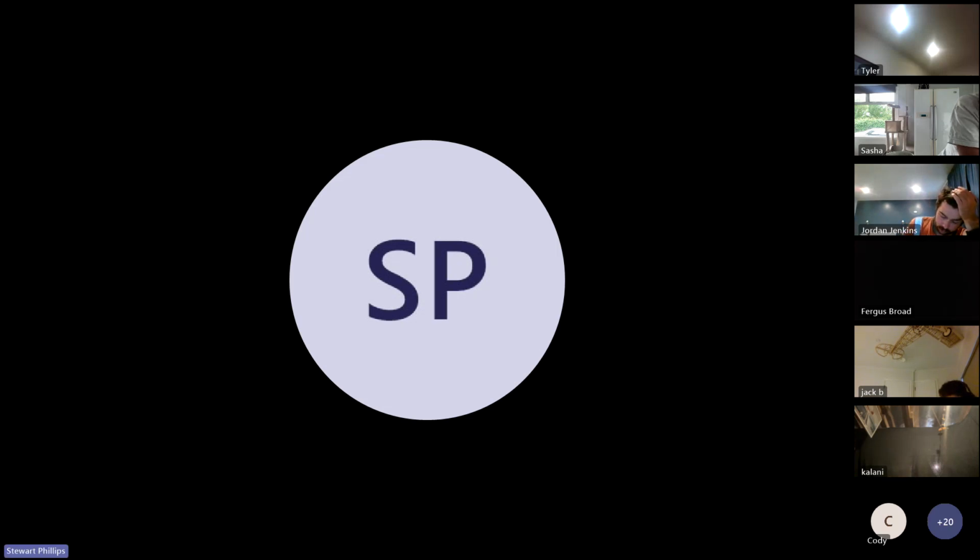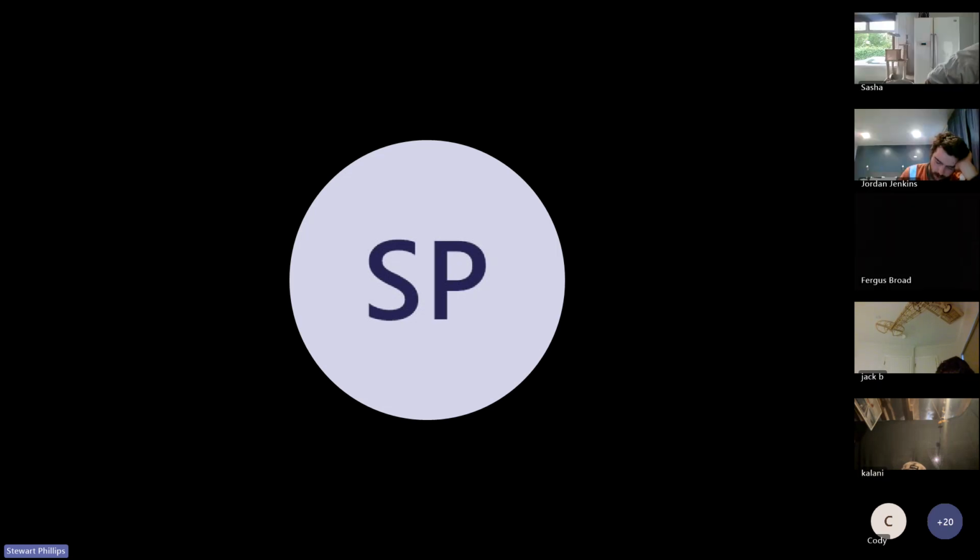So yeah, for our part, when we're doing work on machinery, we need to use the test before touch and prove test prove. So test the circuit before we work on it, prove our meter works, test the circuit is isolated, prove our meter still works. So we prove it on a known live source, we test the circuit that's supposed to be dead, and then we prove our meter's still working on that same live source.